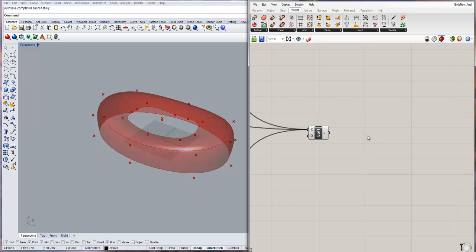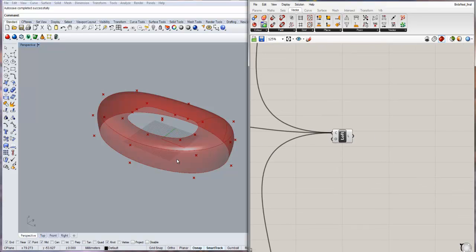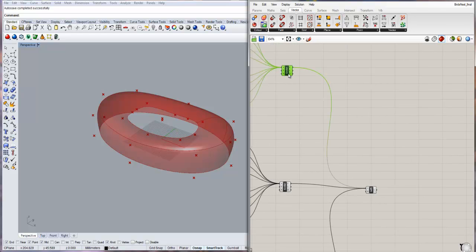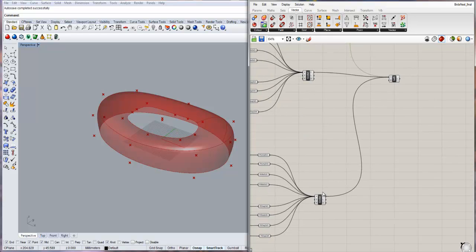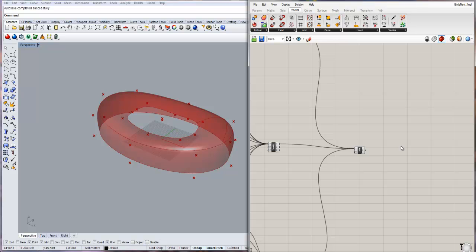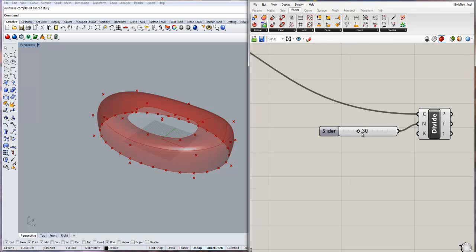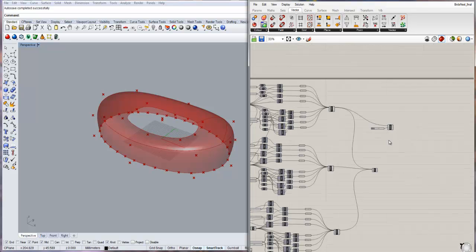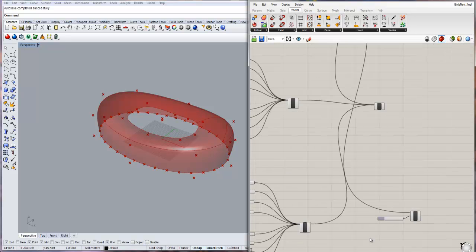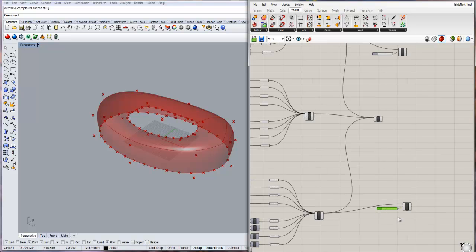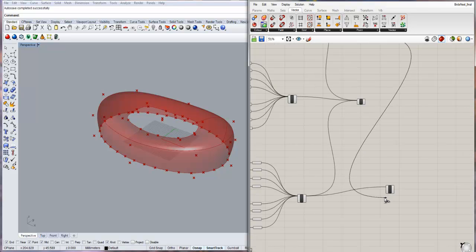After we have this lofted surface, we will make the diagonal curves that run through it. To do that, we have this curve at the bottom, and this curve at the top. So I'll use divide curve for this curve, connect this curve to curve, and give a number of 30. So you see the curve is divided into several points, and I'll use the same method for the opening curve. So here we have another set of points. Slider, I will use the same number for these curves.